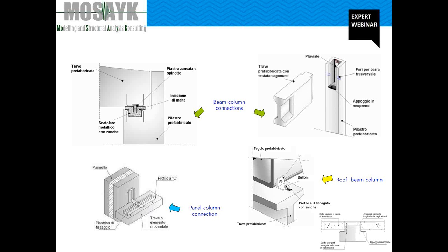Although the pins are tightened into steel blocks, which are anchored into the concrete element by welded bent steel bar, the tensile resistance of the connection can be considered negligible because of the very small length of the pins.